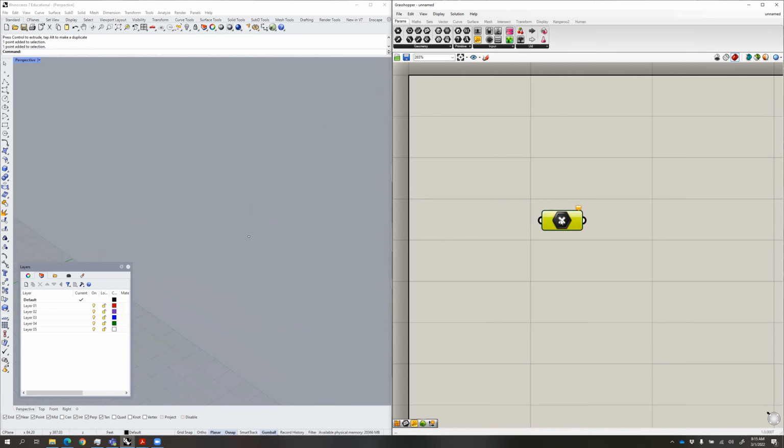You right click on the component, and then there is this thing called set one point. You can also set multiple points. We'll do both of those examples in a second, but let's do one for now. So you click on that, and then you can basically set that point like so. And you see what happens is now the component has hosted the geometry. So if I select this component in Grasshopper, you'll see that it highlights the preview in Grasshopper, turns like a little green dot.